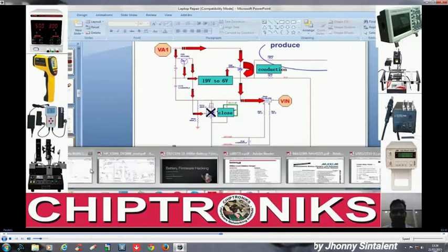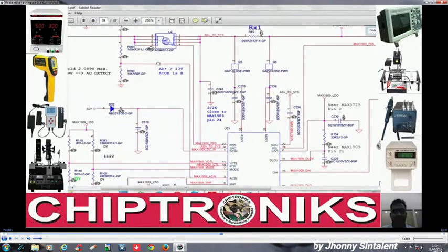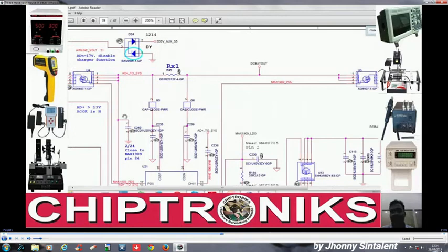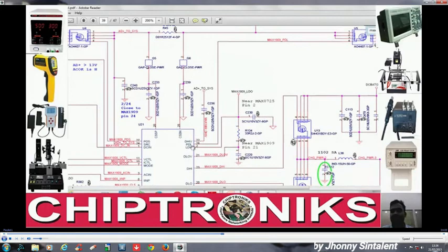core board, we see in a dual core board, this is a P channel MOSFET, so it will treat it like a diode. This adapter volt will come across this, and it will be treated as DC bat out, and when adapter is present, this MOSFET will get turned off from this PDL signal, right? PDL and PDS is very important, and we'll look into detail after we study the data sheet of this. Okay, so let's go to study the smart battery, smart adapter section, and then we'll come back at studying the data sheet of both of these charger ICs.